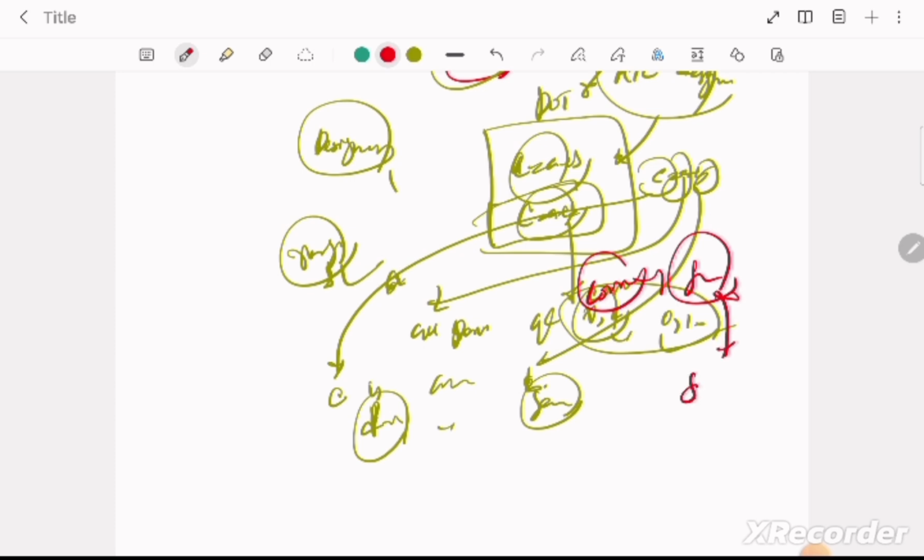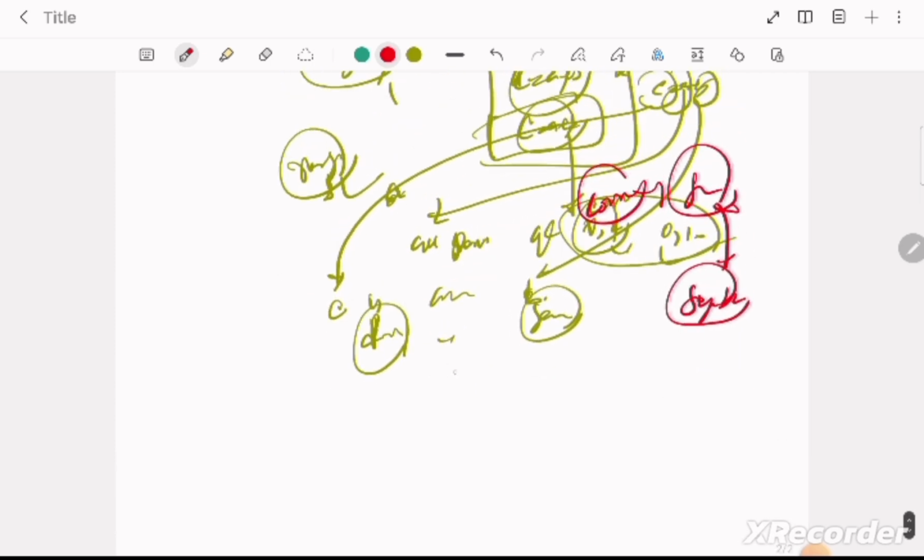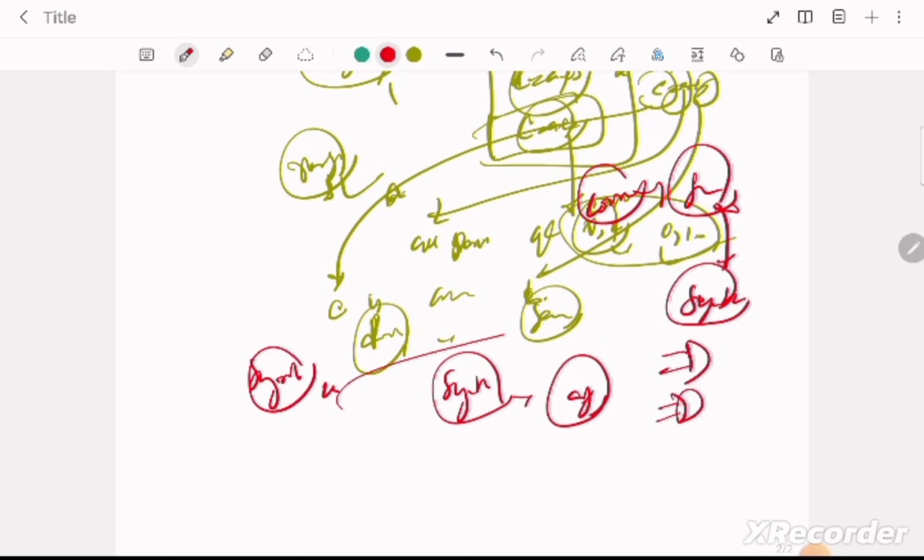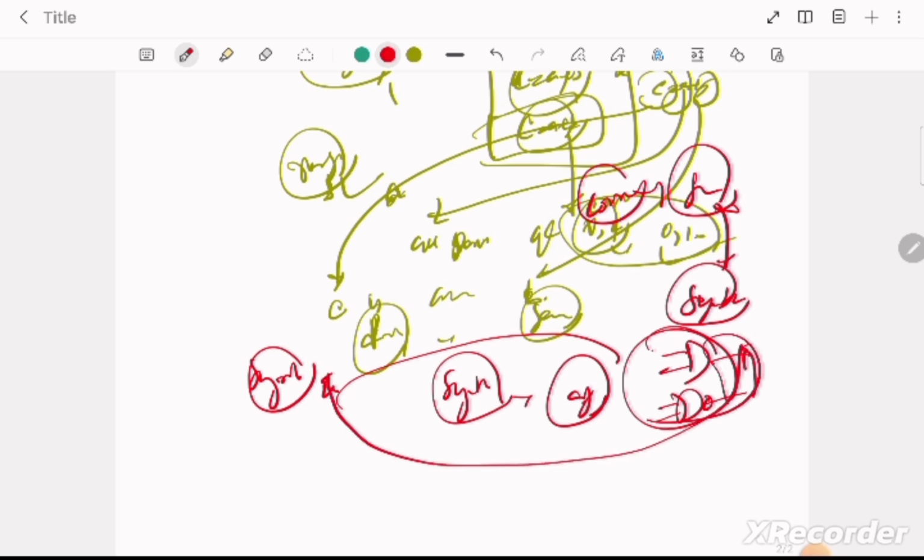What do further steps mean? Synthesis. Now we will synthesize the design. When we synthesize this design, after that we also need to do the verification. Why? Because the netlist that we got might have some modifications made by the synthesis compiler, and our output might not come out correct. So we need to do the verification of the design after this netlist also. So the verification will be done two times.